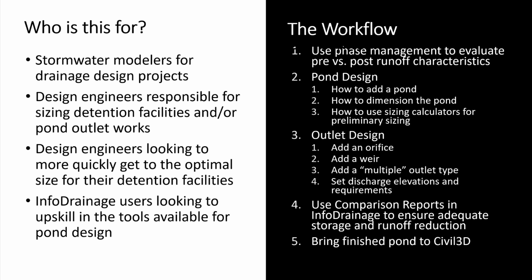But today's workflow is going to be a little more in-depth in terms of how to actually build ponds in InfoDrainage. What tools are available to you in InfoDrainage for the sizing and routing of these ponds, as well as what tools are available to you in this tool for designing outlets. So we'll take a look at a few different items there. We'll look at the different outlet types.